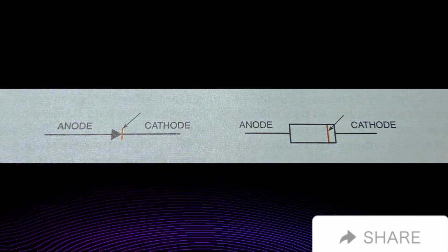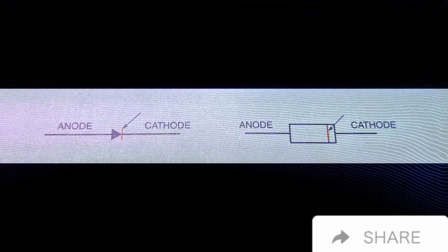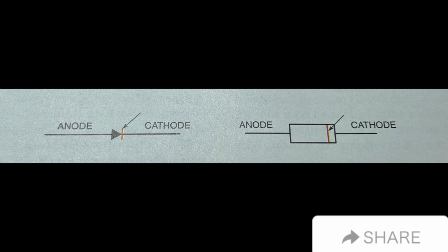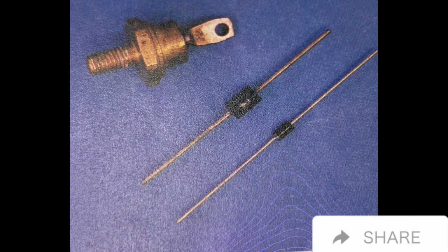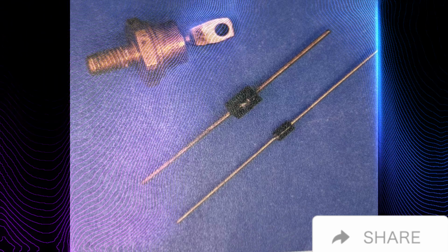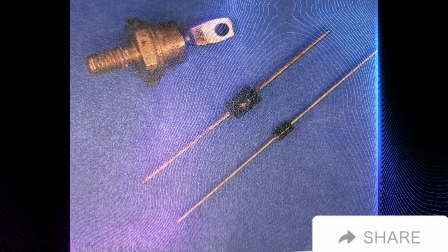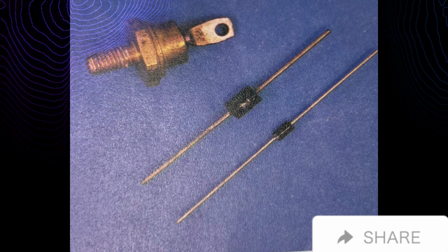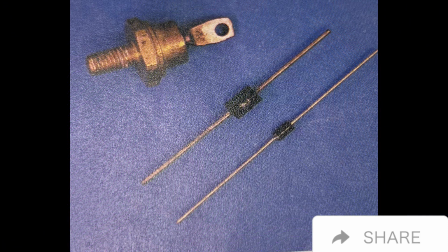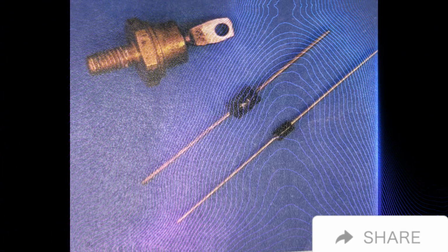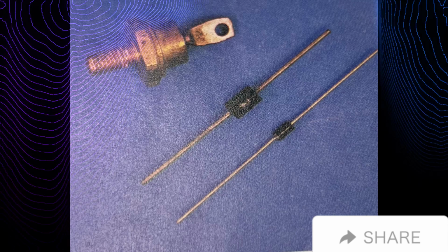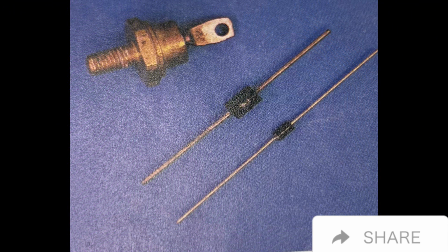Large stud diodes, for example, often have a printed symbol on the case to show proper lead identification. Small plastic case diodes often have a line or band around one end of the case. This line or band represents the line in front of the arrow on the schematic symbol of the diode.